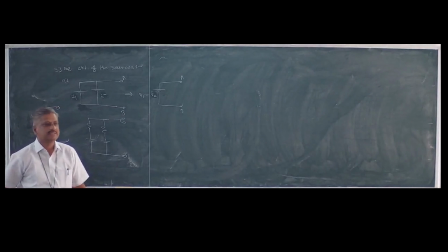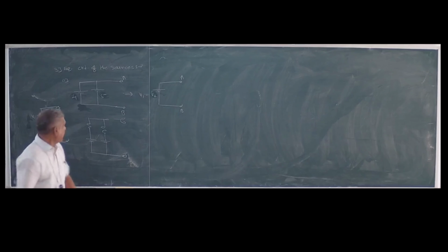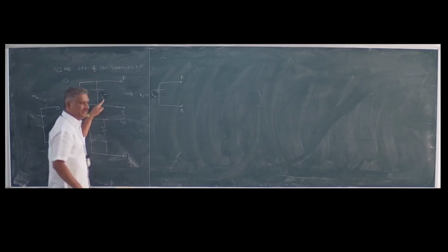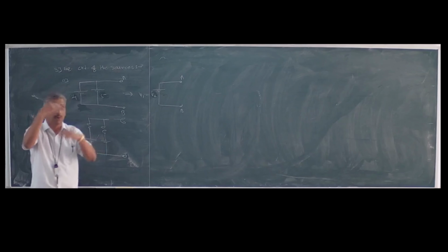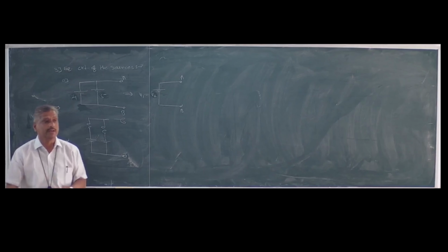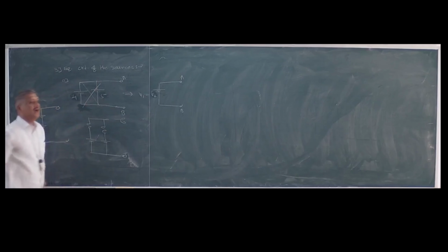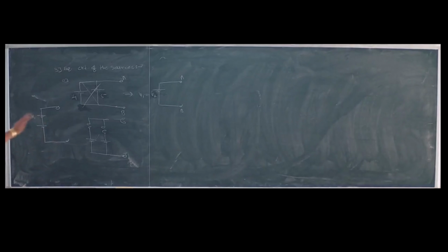What is the basic rule of the parallel circuit? Voltage across the parallel element must be the same. But if we connect 4 here and 5 here, the voltage across both branches may not be the same, and it will overload one another. It means if we do this, it is an invalid network, and the theorems or whatever theory we are studying are not applicable to it, and this circuit may not be stable. One or the other day it will get damaged.